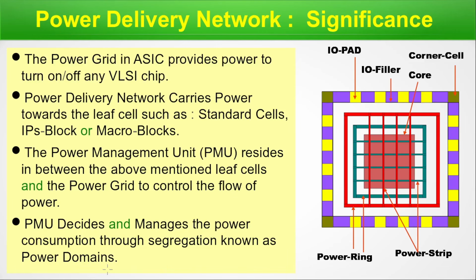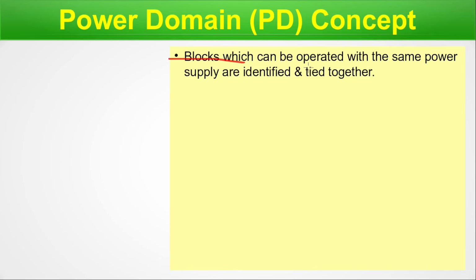So here we are done with the power delivery network and we have plunged into the power management unit and we will further plunge down into the power domains in the next slide. Here we will talk about the power domain concept, that is abbreviated as PD. Blocks which can be operated with the same power supply are identified and tied together like this.